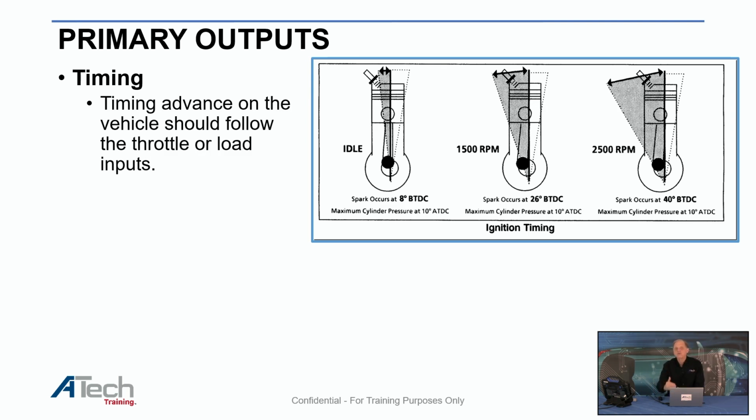If I go to 2,000 RPM and hold it there, I should have the same vacuum or more. The reason is more, because I had a timing advance. So you can look at an issue there also. If I don't have proper timing advance, I won't get the increase in vacuum. This is something to keep in mind. If you have advanced timing, you have more vacuum. If you have retarded timing, you have less vacuum, and you also have a change in pressure in the intake manifold. It will change in the correlation. So there's something else you need to look at as going across.